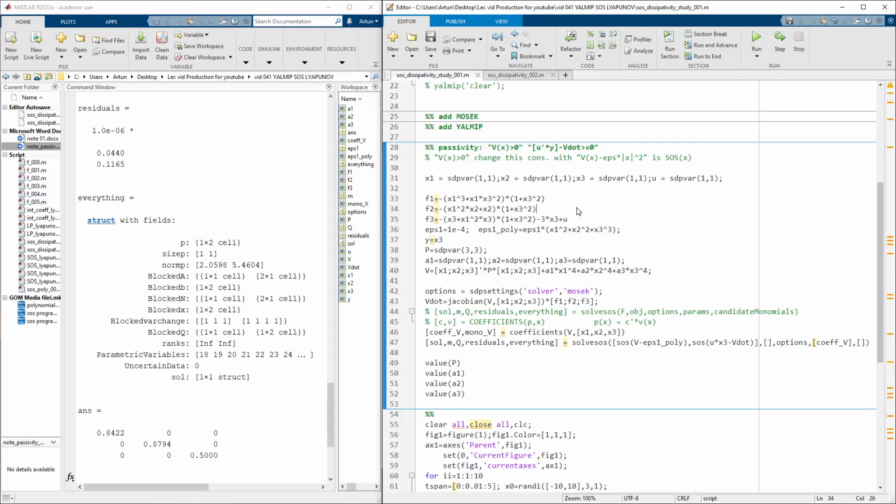If we have an input-output nonlinear dynamical system, 1, if it is passive, and 2, if it is zero state detectable, then by using a passive memoryless static function, we can construct some type of negative feedback loop, and we can construct a globally asymptotically stable feedback interconnection. Okay, it sounds complicated, but it's not.